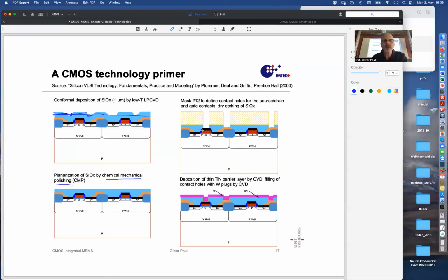So this is kind of unrealistic. So what is achieved here with the drain and source contacts is also applied, of course, to the gate contact behind. And what you now see is that the oxide is open, and now we can do first deposition of a titanium nitride barrier layer, and then a blanket deposition of tungsten is done. So there is titanium nitride, very thin.